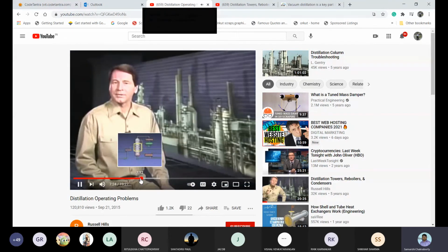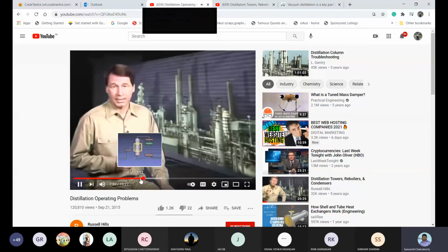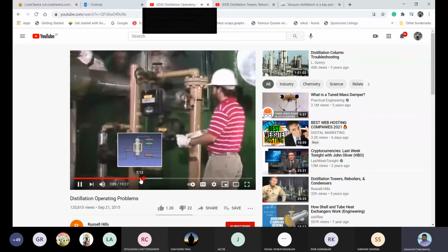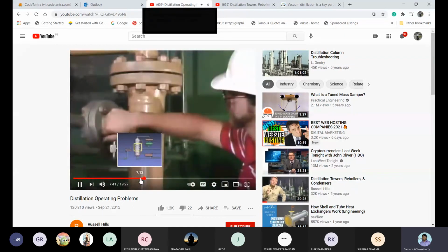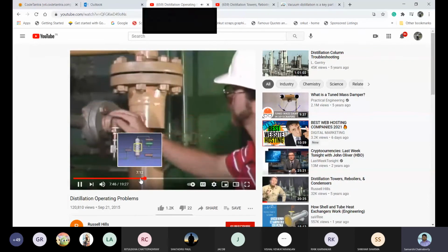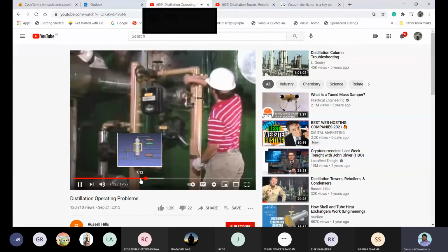Many of the problems that affect a distillation system can occur during startup. For that reason, operators should be on the lookout for problems such as improper feed rates and temperatures, instrument failures, and residue buildup in feed and product lines. In vacuum distillation systems, operators should also watch for leaks. A vacuum leak will cause changes in the temperatures and pressures in the column, which can reduce the efficiency of the system or stop the distillation process altogether.